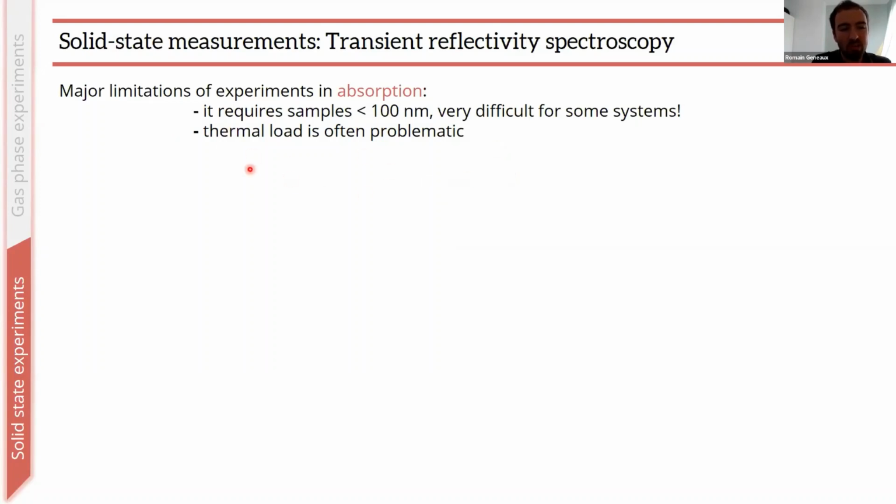And the second one is that since those are so thin, the heat that you deposit with the laser stays there pretty much. You don't have any way of evacuating that heat. And so the thermal load is very, very often problematic. Even when we look at 1 kilohertz, usually we just put too much heat in the system, and we have to find ways to chop down the repetition rate or to wait for it to cool down.